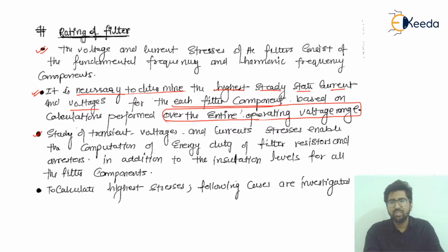The study of the transient voltages and current stresses enables the computation of the energy duty of the filter resistors and the arresters, in addition to the insulation levels for all the filter components. It is specifying that when we are considering our filters, we take into consideration the insulation level.